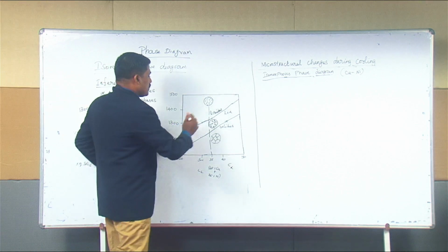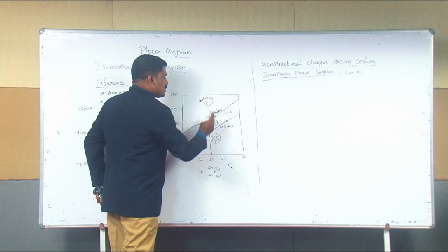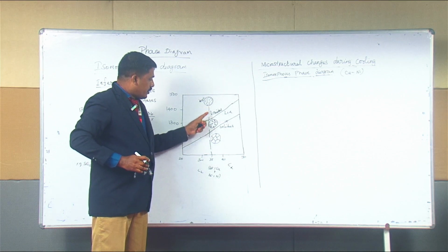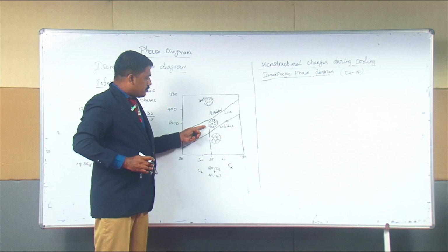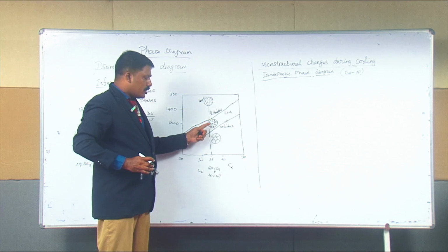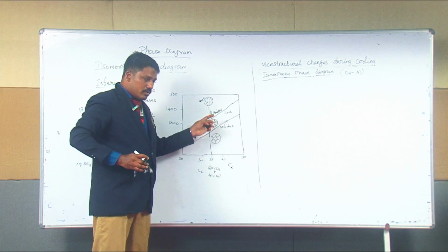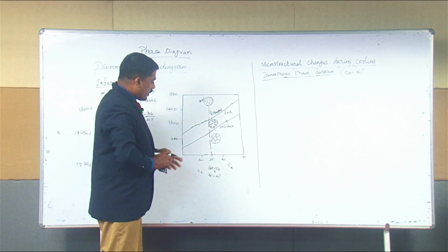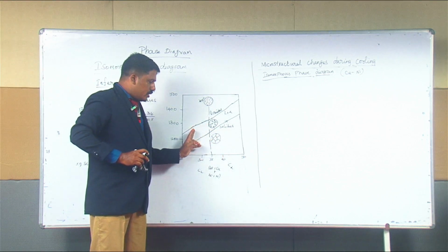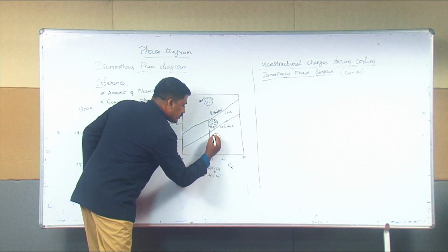At 1450 degrees Celsius, the given alloy system exhibits the liquid state, and then when we cool it, or reduce the temperature, solidification starts. Between these two boundaries, in the L plus alpha region, the solidification slowly increases, and after the solidus boundary, the given system is completely solidified.